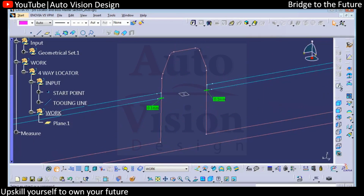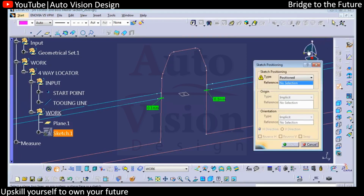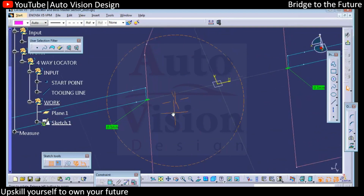So we need to create a sketch. Always we select the position sketch, so we'll select that position sketch over here. Then you can select a projection point. Then as always said, vertical here, horizontal here. So we'll reposition that vertical and horizontal, and then we can create. Before creating that we need to measure the dimension. So dimension we can check for how much we need.